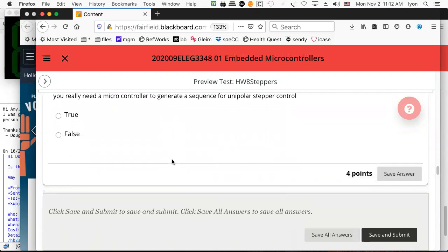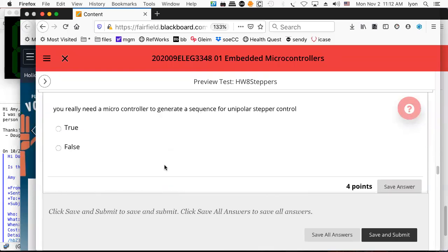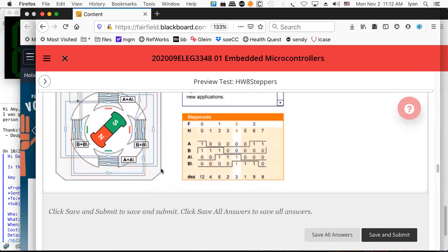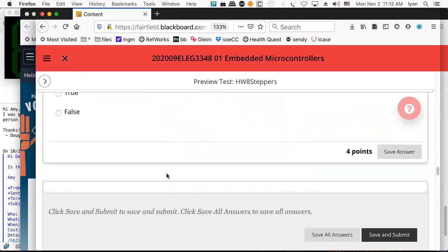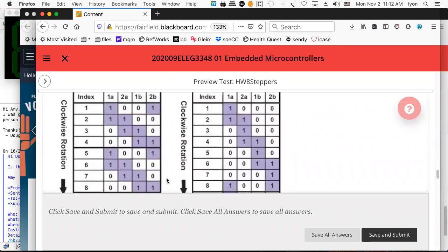Although it could, I don't know. So then here it says, and by the way, I've designed these for stepper motors just using normal TTL, the 7400 series MSI TTL. It's not that hard. Make a counter, you decode it, there you're done.